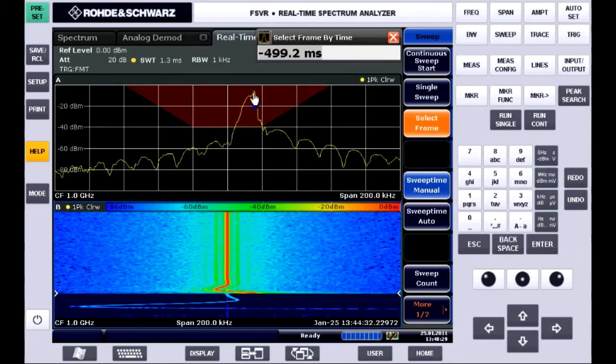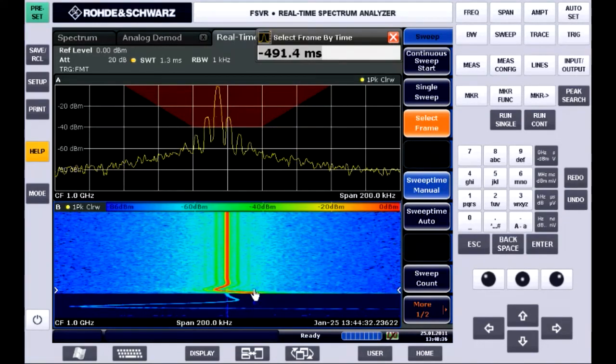So now we can see we're about that 16 kilohertz above when the power turns on, just like we saw in K7. Now we can go down and see that we're 6 kilohertz low, and we settle out. But look what else we can see that we couldn't see before. Not just the frequency of the settling, but these sidebands. I've seen other transmitters where the sidebands are much worse than that and got a lot more attention from the customer. Alright, so now we can scroll up through time.